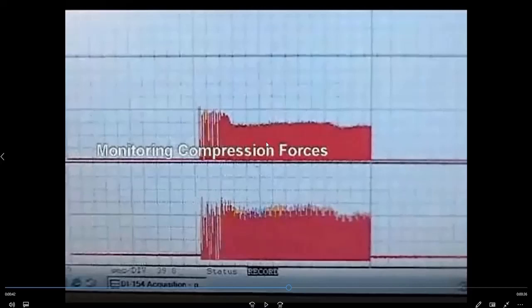If we lower the distance they travel inside the die cavities, then we will have lower pressure, right? But if you don't have good filling inside the die cavity, what will happen?